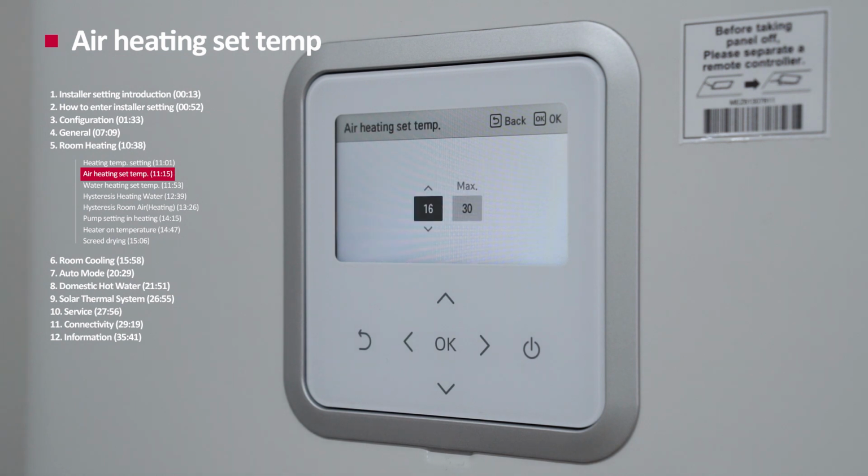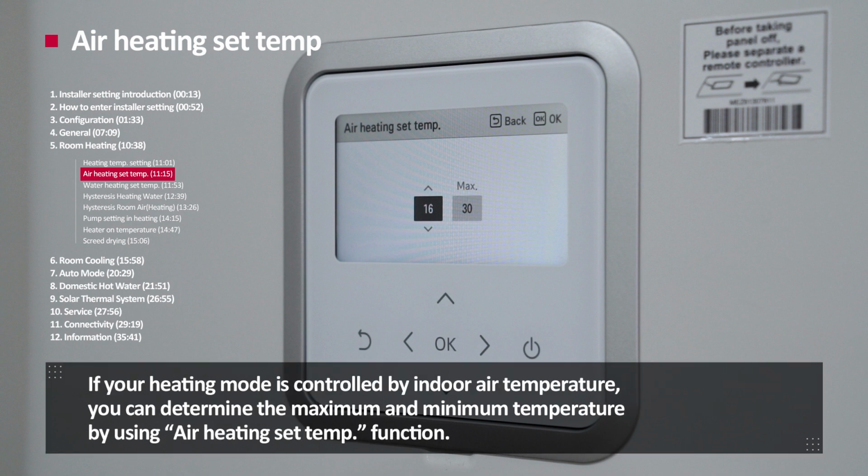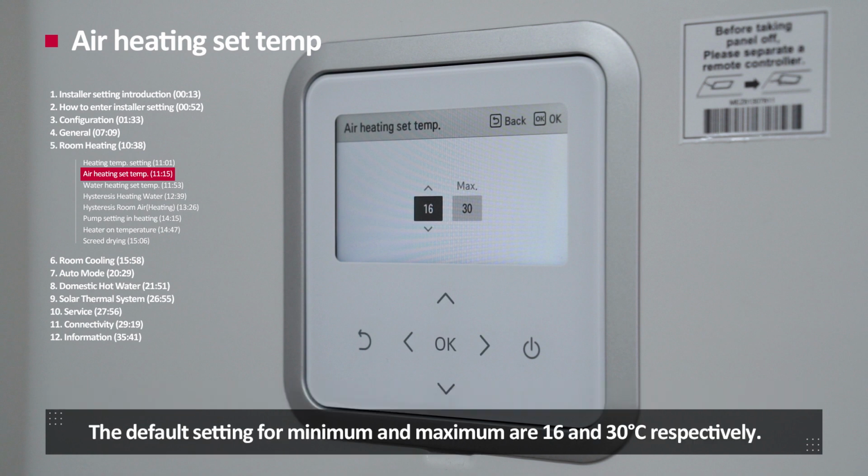Air heating set temperature. For the heating mode, the heating temperature can be controlled based on the indoor air or water temperature. If your heating mode is controlled by indoor air temperature, you can determine the maximum and minimum temperature by using the air heating set temperature function. You can set the minimum temperature between 16 and 22 degrees Celsius, and the maximum temperature between 24 to 30 degrees Celsius. The default settings for minimum and maximum are 16 and 30 degrees Celsius respectively.